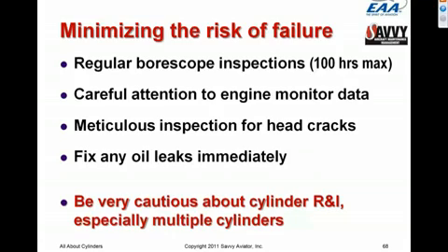We want to take a look at cylinders every 100 hours at most with a borescope. Specifically, the borescope will give us around 100 hours of lead time before an exhaust valve fails. So if we aren't looking at the valve at least every 100 hours, there's a chance that we'll miss a hot spot and have the valve fail on us, and we don't want that to happen.